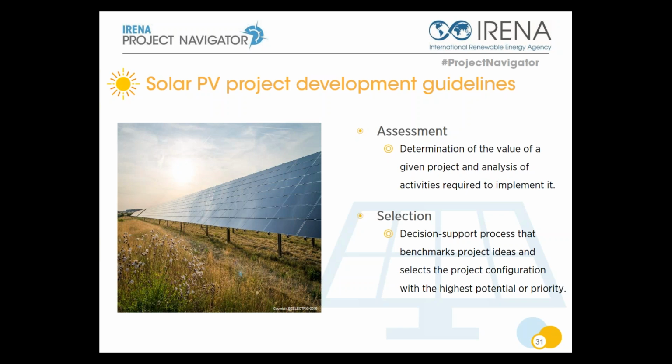You will find in the guideline that, for example, well-maintained sensors on an on-site ground measurement meteo station can measure the solar resource with an accuracy of ±3 to 5%. This is already very granular in terms of quality, but you need to implement maintenance procedures.